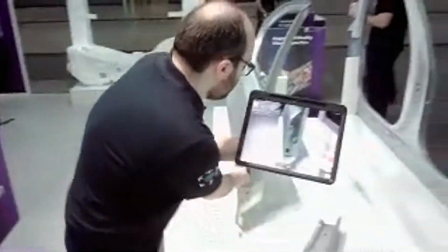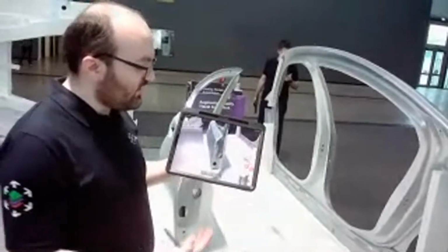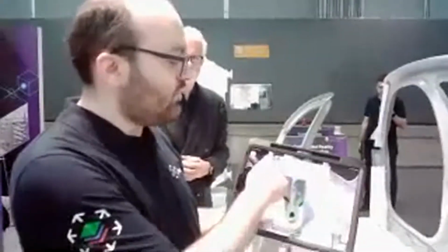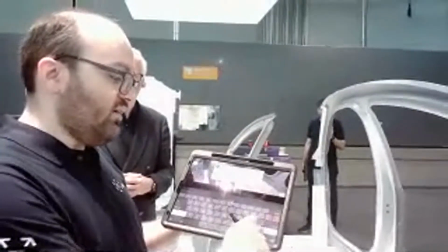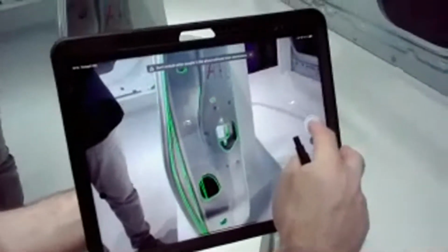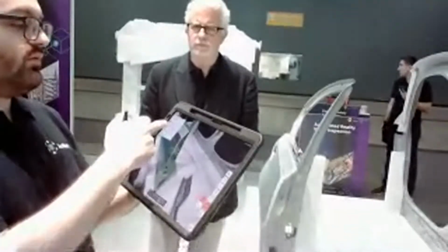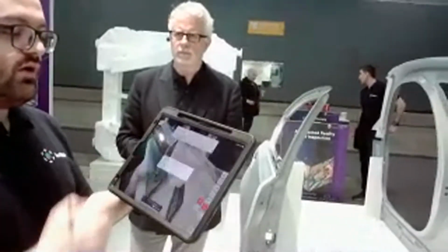For example, here we have some spot welding points, and now it's not marked in our CAD data, but if we mark this data on our CAD data, then with the inspection template, as we know, we can say this point is okay, and we can say in tolerance, for example. And we can take a picture as proof that what we did is okay, and then save, and we can create a PDF report of this inspection.